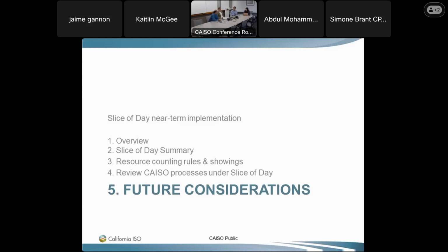Thank you. And I just want to point out too that the 0 megawatt issue, you really only see this impacting the solar resources, and it's not across all months. So I think even if you look at September in the files that the PUC put out, there are non-zero numbers in hour 19, for example. So this would only impact some of the winter months.